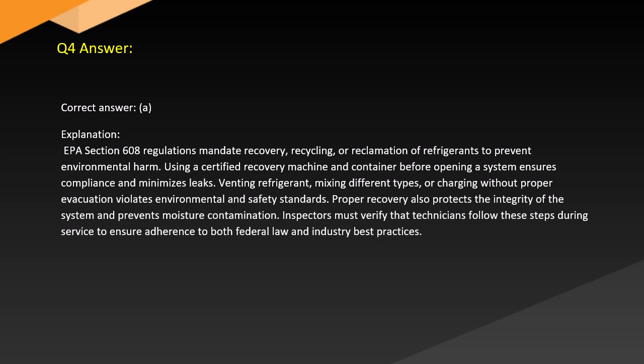Venting refrigerant, mixing different types, or charging without proper evacuation violates environmental and safety standards. Proper recovery also protects the integrity of the system and prevents moisture contamination. Inspectors must verify that technicians follow these steps during service to ensure adherence to both federal law and industry best practices.